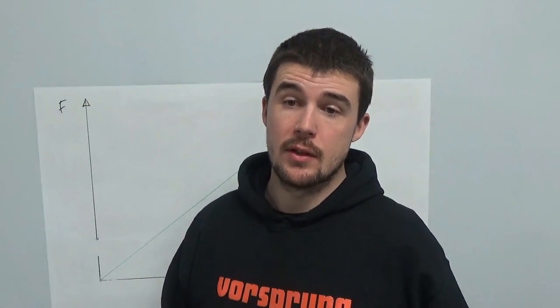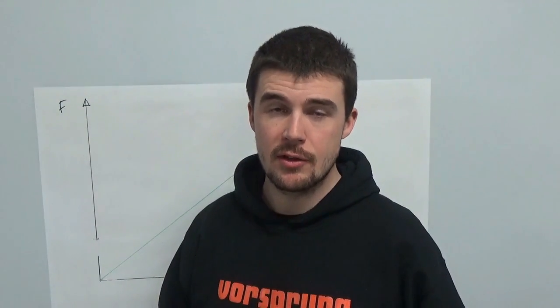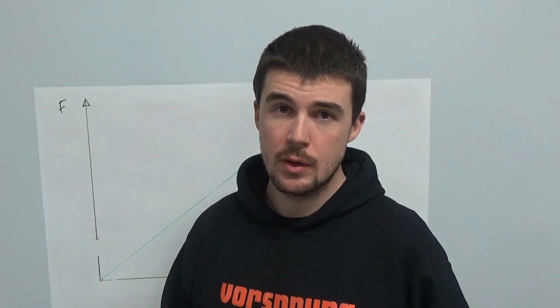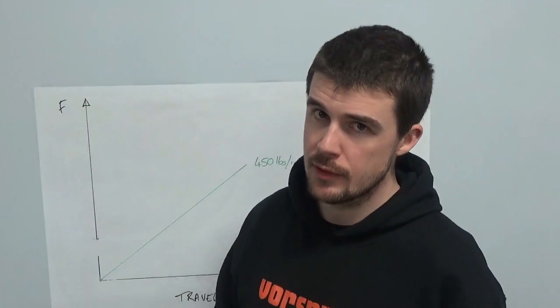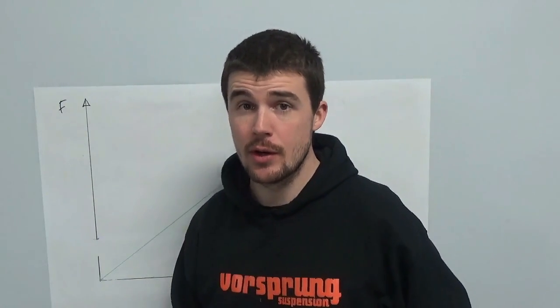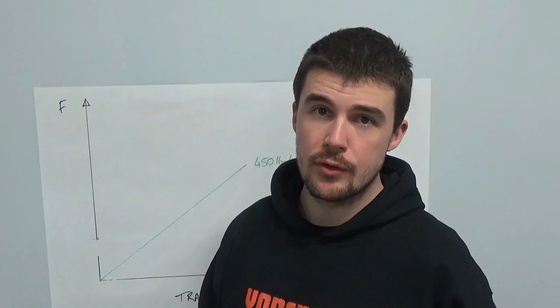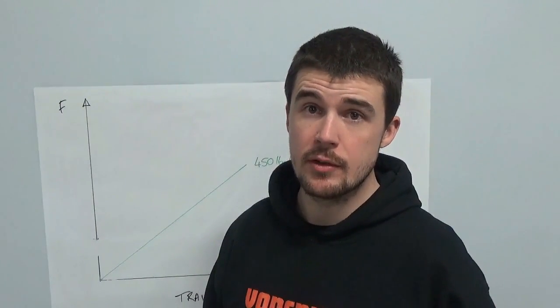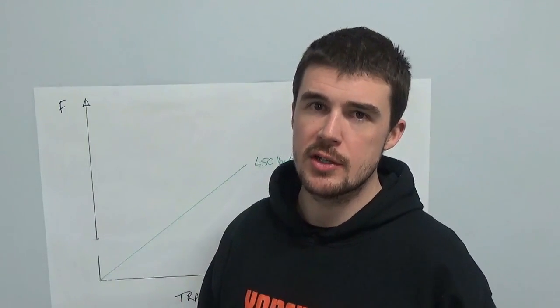However, if you are feeling like your titanium spring is softer than your steel spring, either it's placebo or you have a different spring rate. Alternatively, you have a different amount of preload and you're measuring a different sag value. However, spring rate is not material specific, it is defined as change in force over change in distance. Whether that's steel or titanium, you will not change the performance by changing the material.